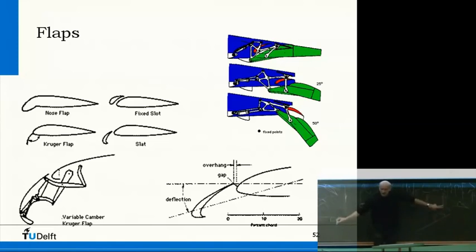So if you put in a vortex generator just in front, higher velocity energy gets into the boundary layer so that the flow will not separate, but will follow the contour, right? So whenever you see these things, this is a precaution. Whenever the situation might be such that the flow would separate here, these vortex generators prevent separation. And the same goes for these slots. It's new air with new energy coming down here.